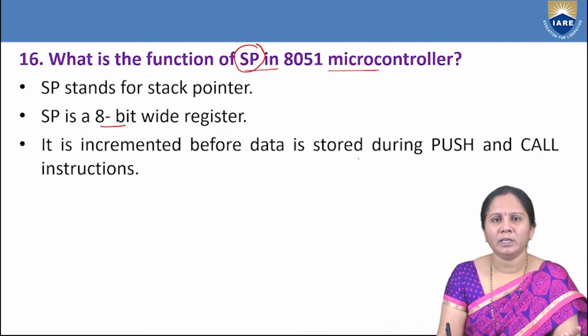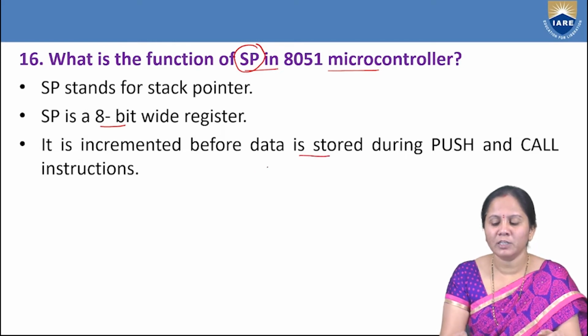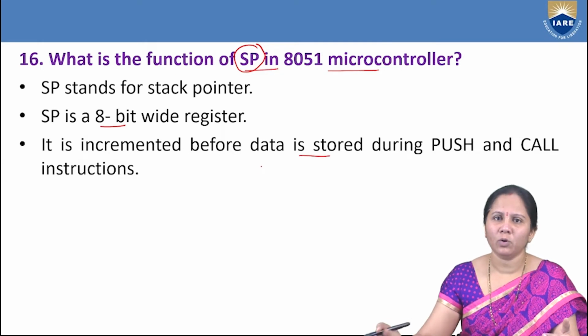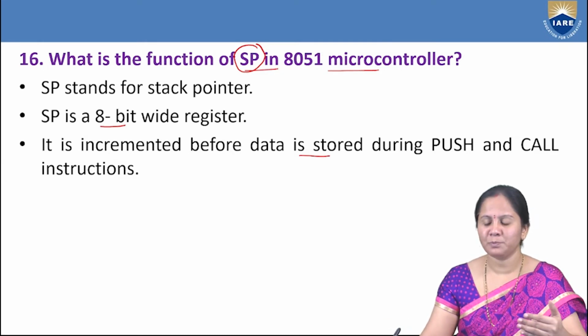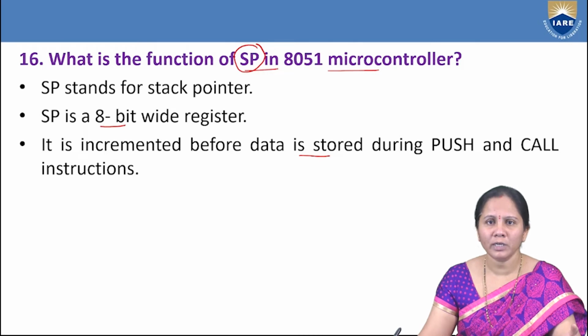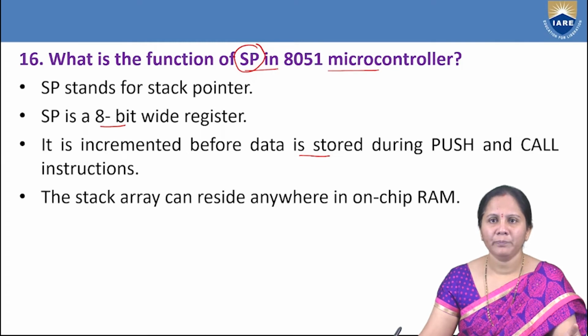The stack pointer register contains the address of the top of the stack, and it is incremented before data is stored during push and call instructions. So when push and call instructions are executed, the stack pointer will be incremented.